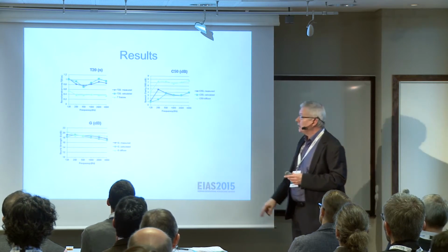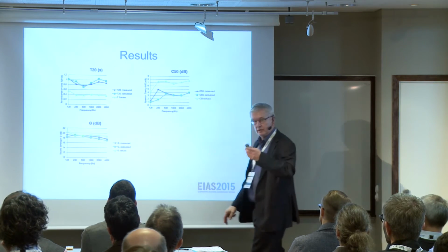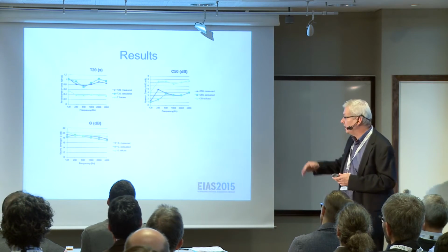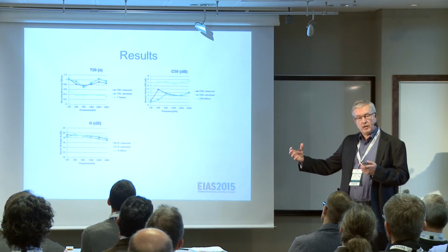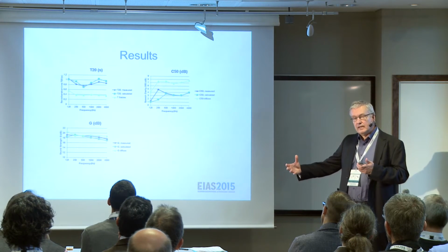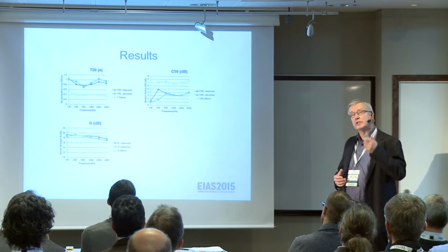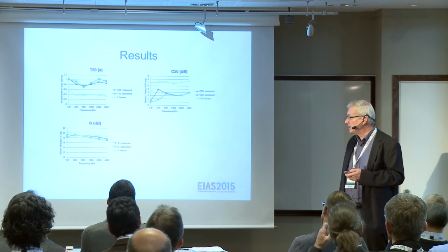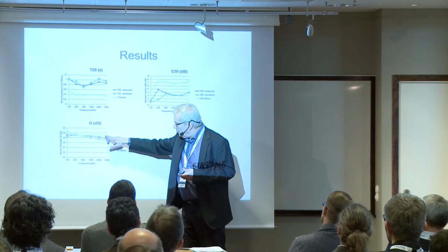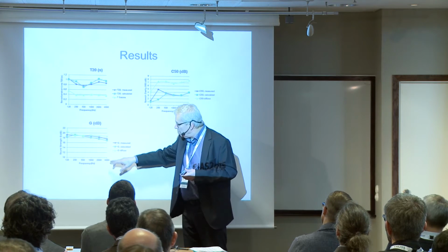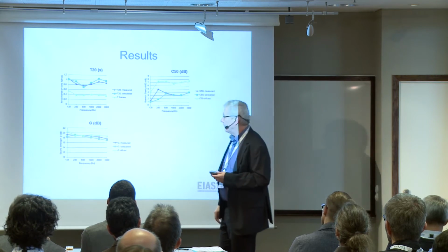When we look at strength, the differences are not that large, as we heard Jack Harvey talk about yesterday. That's because when we measure strength, we normally have a constant sound power source, and that means that during this type of measurement, steady state measurement, the sound field is quite diffuse, even if we are in a room with ceiling treatment. But nevertheless, there are some differences, and the diffuse field theory overestimates a little bit. The green calculated one is a little bit lower, but quite close.